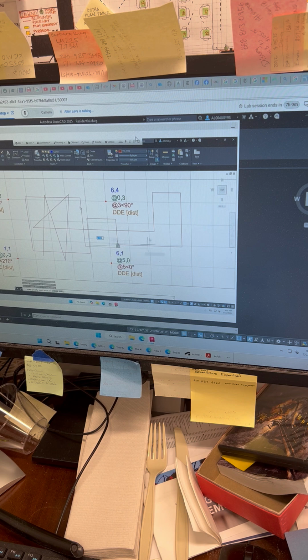And so here's the point: now I am forced to draw perfectly horizontal and vertical lines. Now, this is something that students get a little confused by because their cursor seems to be not attached, and it's not. It's not attached to the end of the line, but wherever your cursor is in either the vertical or horizontal direction is where the line is going to extend to. So sometimes students get confused. They don't understand that their cursor can be down here, and yet the line they draw goes up here.